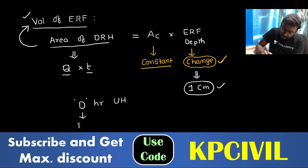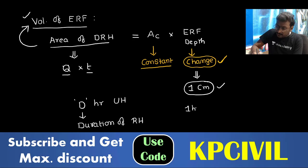D represents the duration of rainfall. So rainfall occurred for 1 hour, 1 hour unit hydrograph, and for a depth of 1 centimeter. So 1 peak discharge is obtained.